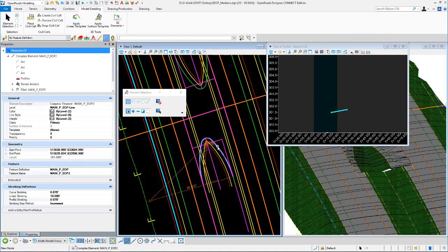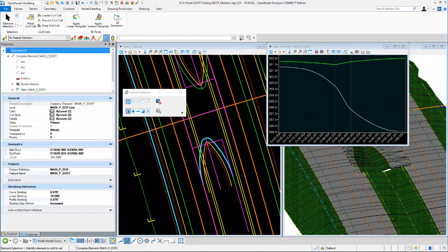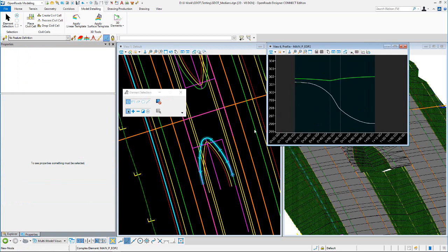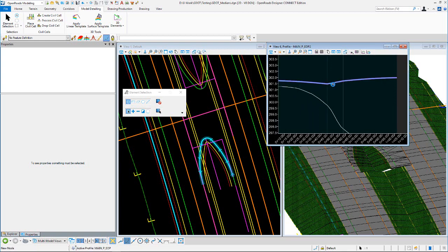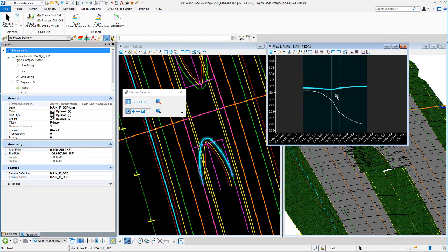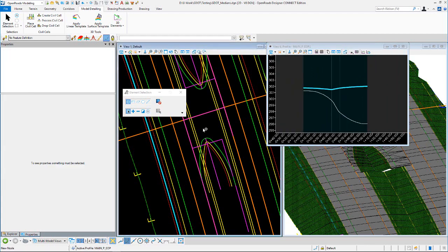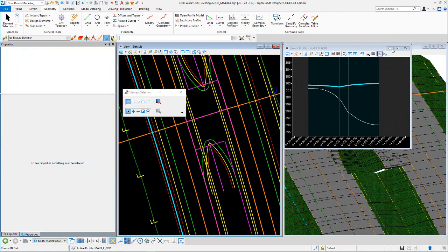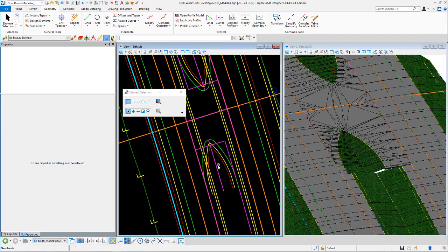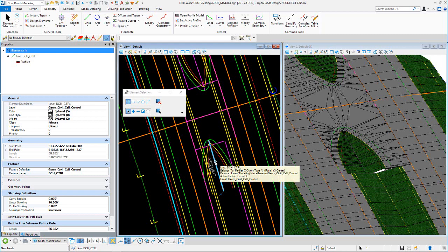And if we come in and look at this and see what that profile looks like, that's at 2% down, 2% down over here, and then just a line connecting that point and that point there. Okay, so really the only other vertical besides that one there that we're going to discuss is going to be this ditch control line here.